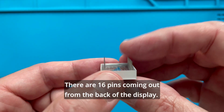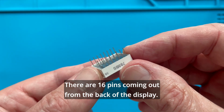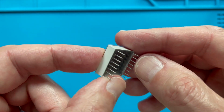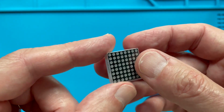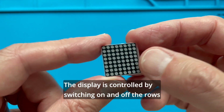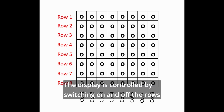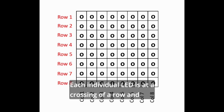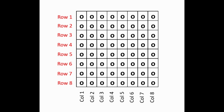There are 16 pins coming out from the back of the display, 2 sets of 8 each. The display is controlled by switching on and off the rows and columns of the display. Each individual LED is at the crossing of a row and a column.